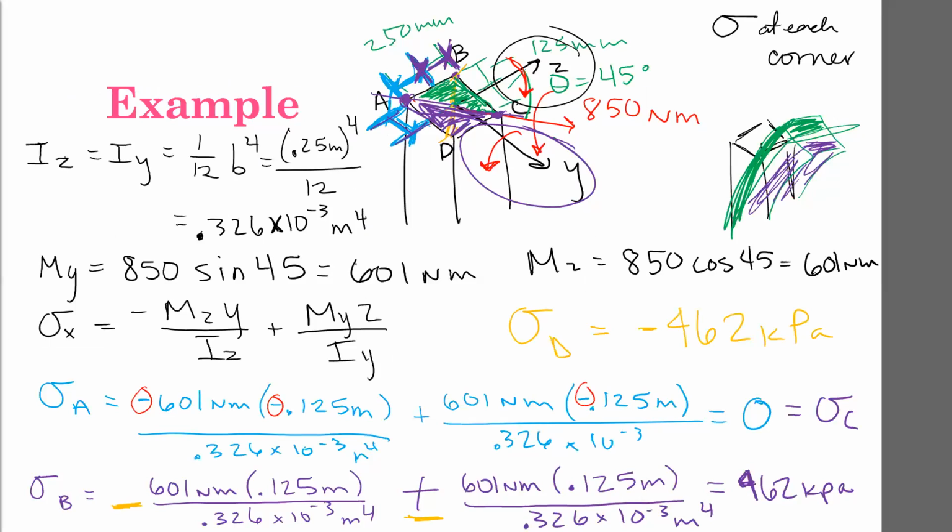I mean, that's for that orientation, so it would be different for each orientation? If the moment is applied on a different angle? Yes, yes. Well, for this particular geometry, because it's a square, no matter how the moment was applied, you would get that that was the same line as the neutral axis. But if this were rectangular instead of square, so these two sides were not equal, then it's going to be a different orientation. That's what I actually meant by memorize them.